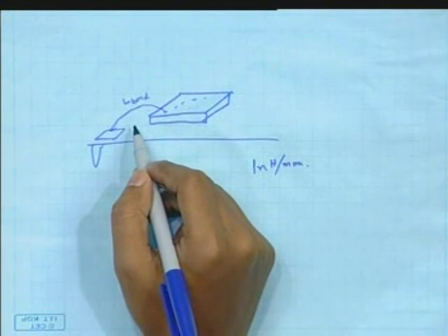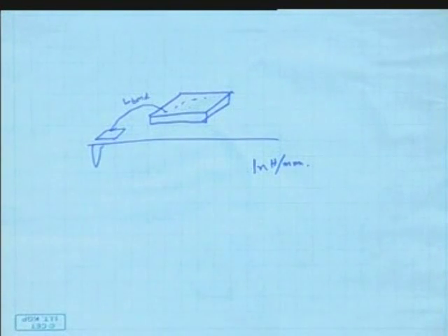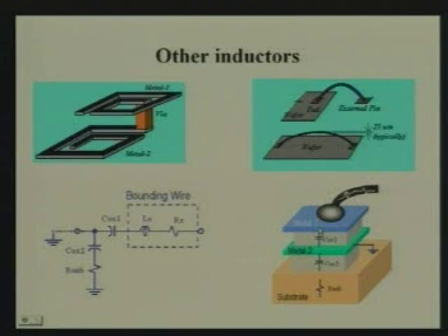the 2 nanohenry inductor. But as the slide shows, we have several losses also associated with the bond wire inductance if we just simply use it blindly, because we need a metal plate down to where the bond wire comes, and if we have subsequent metal layers, that will also contribute extra capacitances. So this is just a circuit technique. If we can ground the bottom layer, see the equivalent circuit here. If we did not ground the bottom layer, the entire capacitance would have come into the picture. However, if we just ground this point, we will have much lesser losses or parasitics.